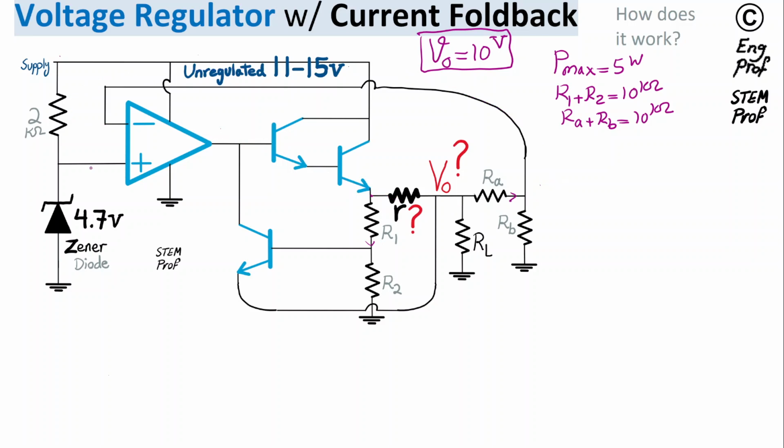As an example, when the positive voltage goes up, the op-amp tries to increase the output, which means the output of the op-amp, and then effectively Vout should go up to compensate, which means then this node will go up, and that would effectively increase the voltage at the negative terminal as well, trying to catch up. So that's an indication of a negative feedback in this circuit.